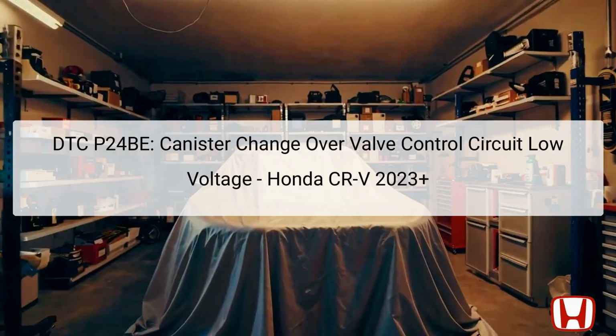The DTC P24BE indicates an issue with the canister changeover valve control circuit, specifically highlighting a low voltage condition. The canister changeover valve, which is integrated with the evap leak check module, is critical in managing fuel vapor emissions. The valve directs fuel vapors to the engine intake and regulates the flow of these vapors to prevent excessive emissions.